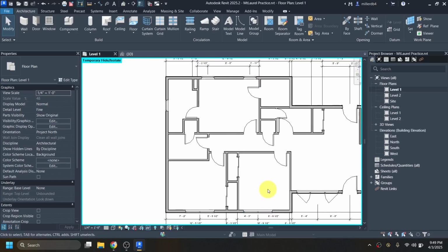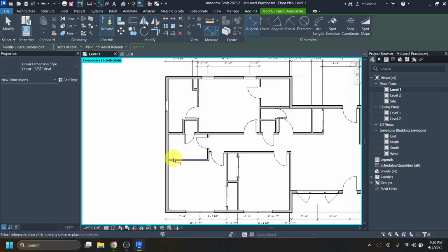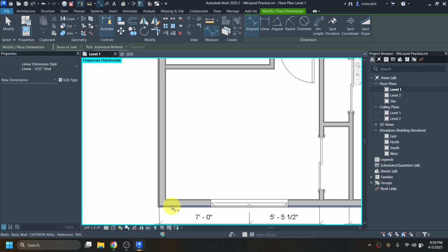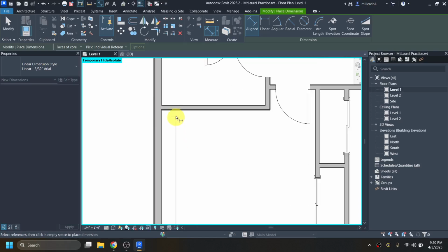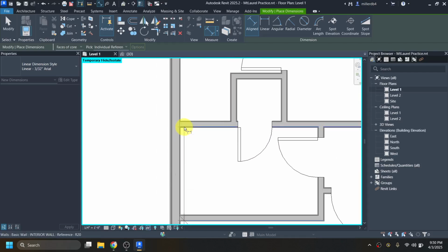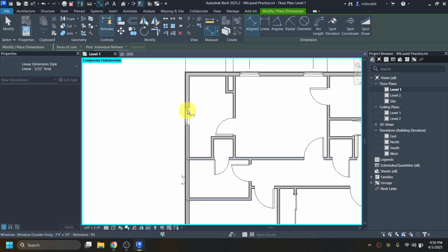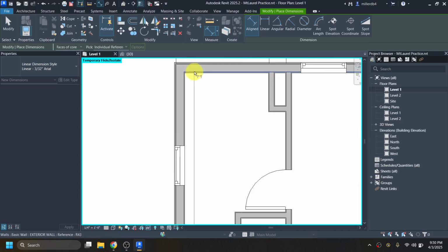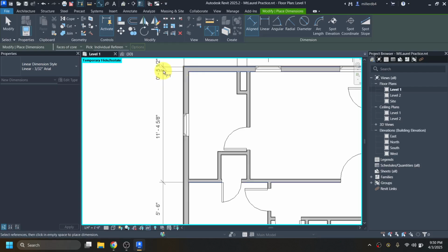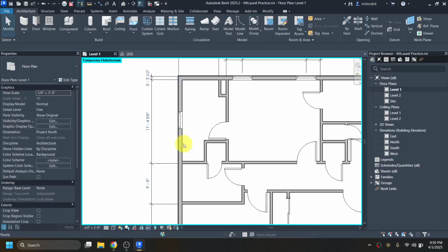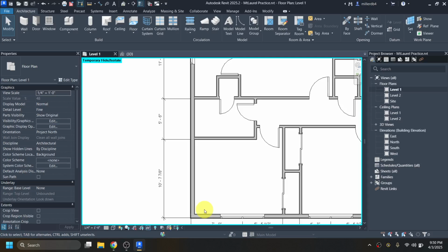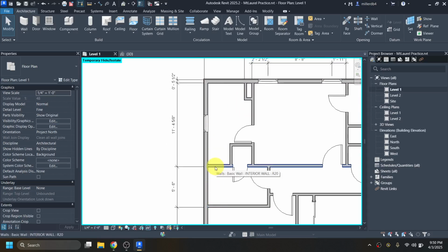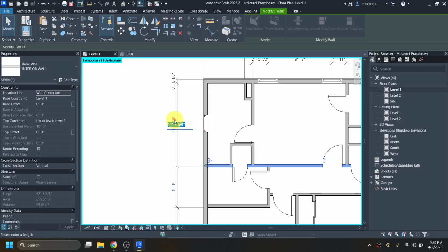One final exterior wall that we're going to dimension is going to be keyboard shortcut, you guessed it, DI. And I'm going to go from face of stud to face to face to inside and outside. Click to place it, hit escape, and then work my way through a line. You could work your way up or you could work your way down, but you want to just kind of work through a line. So I'll click on the wall, adjust this measurement, click on this wall, adjust this measurement,